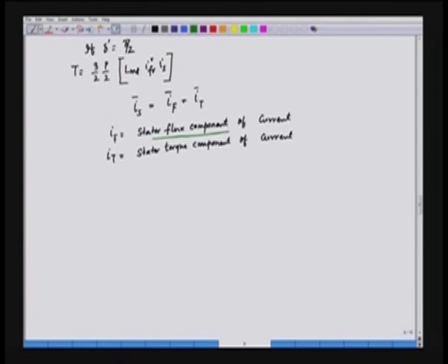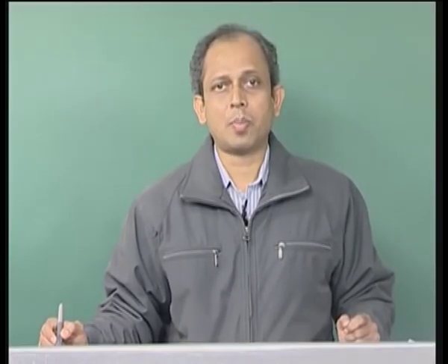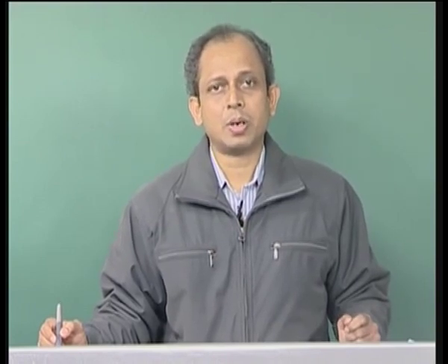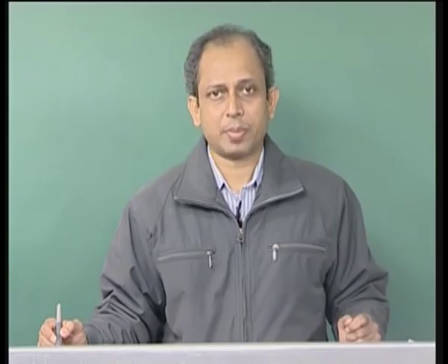And the torque is usually controlled by controlling IT, and that is why this is called the torque component of current. So, in general we can have a block diagram, and the block diagram will explain the various control aspects of the vector control of PMSM drive.